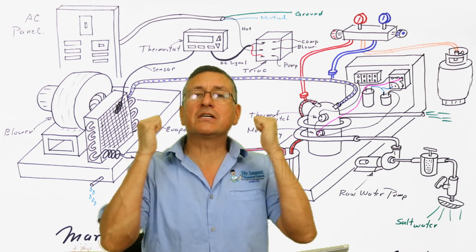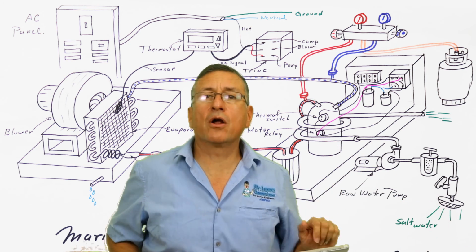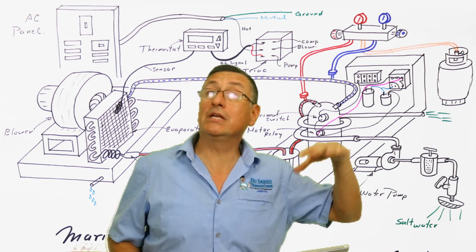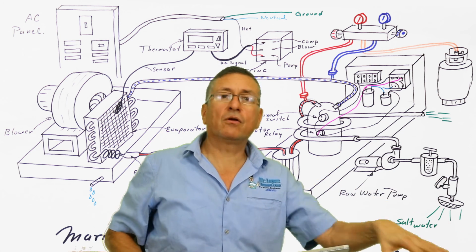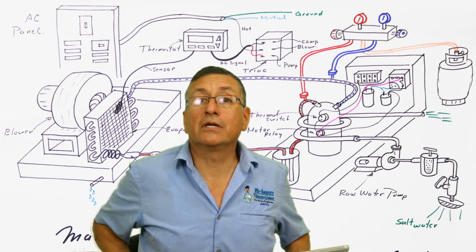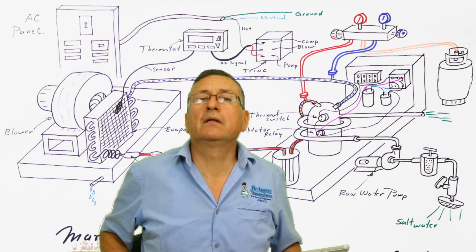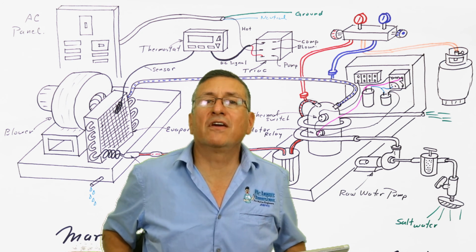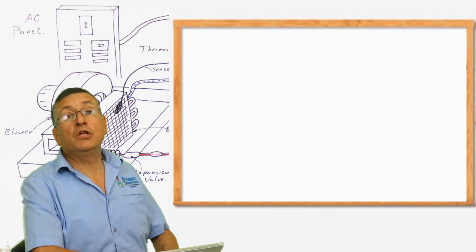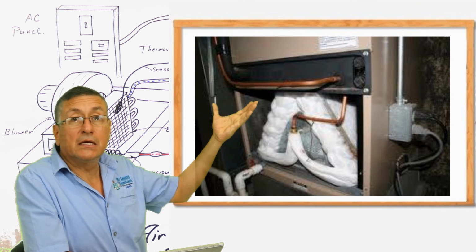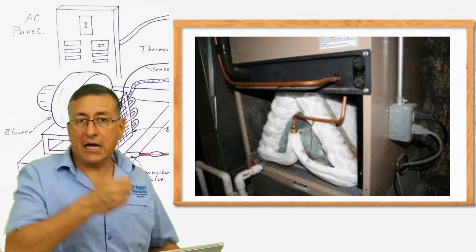But yes, right now we understand the evaporator. We know that if we find water inside of our home or in our car or in our boat, in the cabin, accumulated water in the bottom, and we open the closet and we find a lot of water, we have problems with the evaporator. Check immediately the filter. Oh, I have ice. Okay, that's the problem. The coil of the evaporator is clogged, and what is the next step? Okay, you need to wait until the ice becomes completely liquid. Can I help with a heat gun? Yeah.